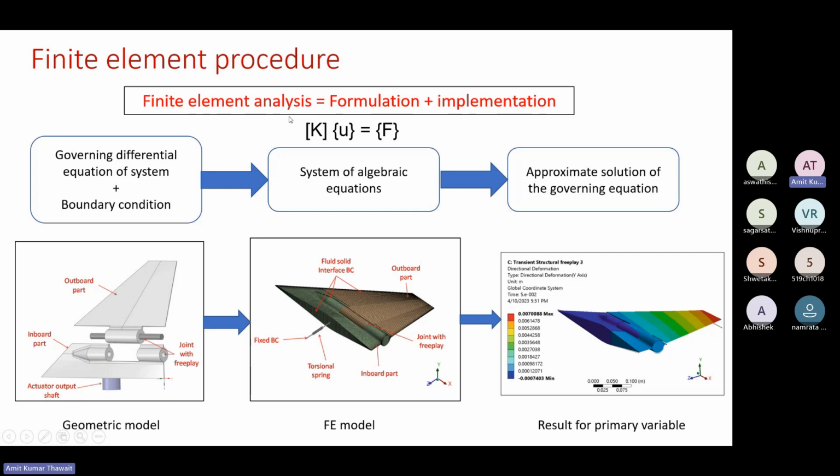One more thing is that finite element analysis, here you can see, is formulation plus implementation. Formulation means we do formulation for these individual elements. We derive the element stiffness matrix, element force matrix, and we decide how many nodes should be there, what degrees of freedom should be there. These are the formulation part.